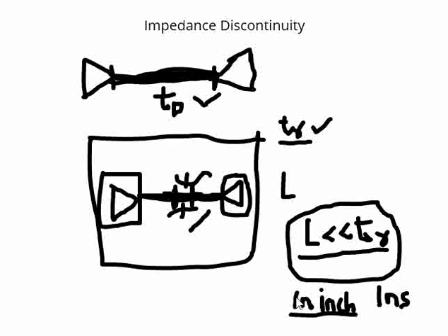in general we commonly treat that the line should have a continuous impedance, and indirectly we eliminate any discontinuity in the impedance and then route the traces. It is definitely possible to have a small impedance deviation, but practically difficult to achieve as we go to higher speeds.